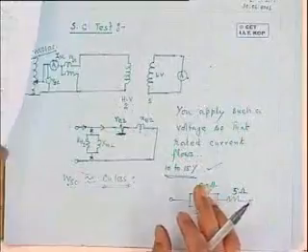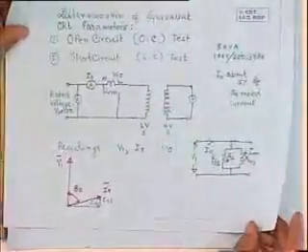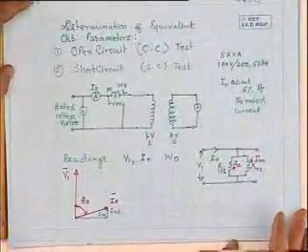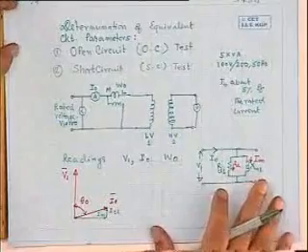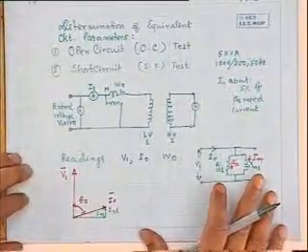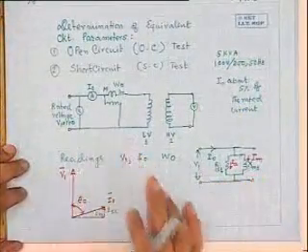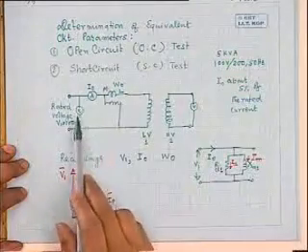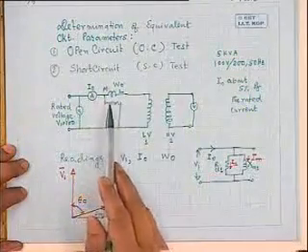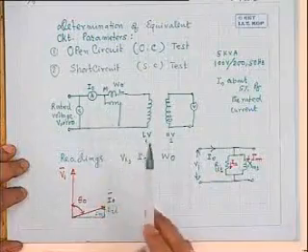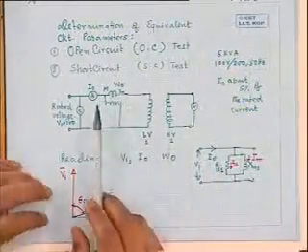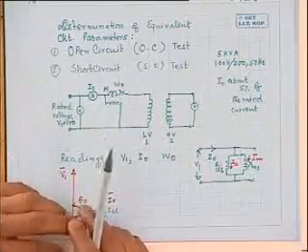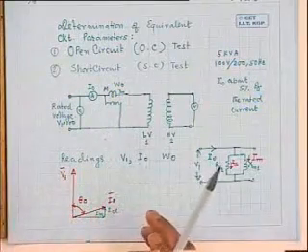Now to conclude this test, similarly I would like to tell about the open circuit test one important thing, that during open circuit test, forget about this equivalent circuit. If you look at the thing physically, during open circuit test, although I am applying rated voltage, the current drawn will be quite small, no load current. So here also the wattmeter reading I am approximating to what?